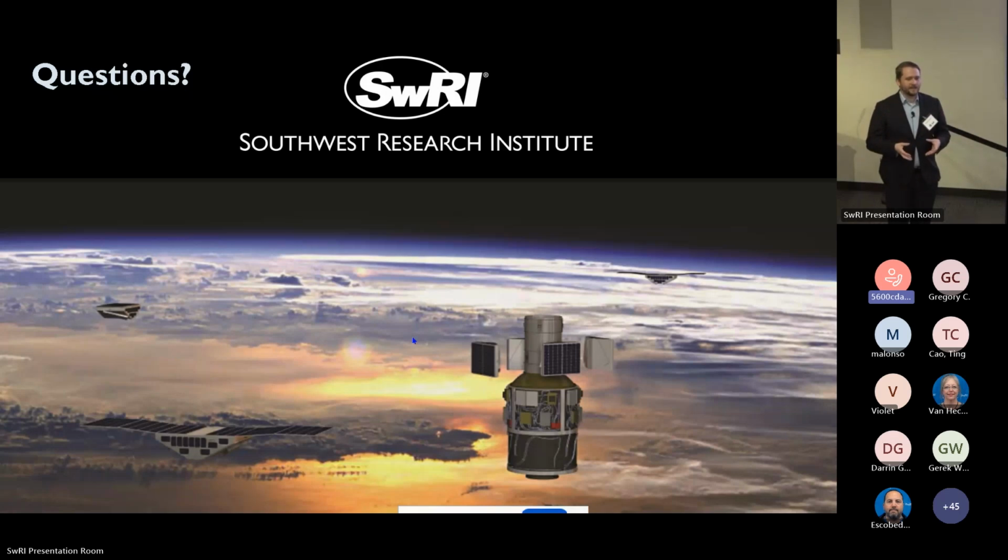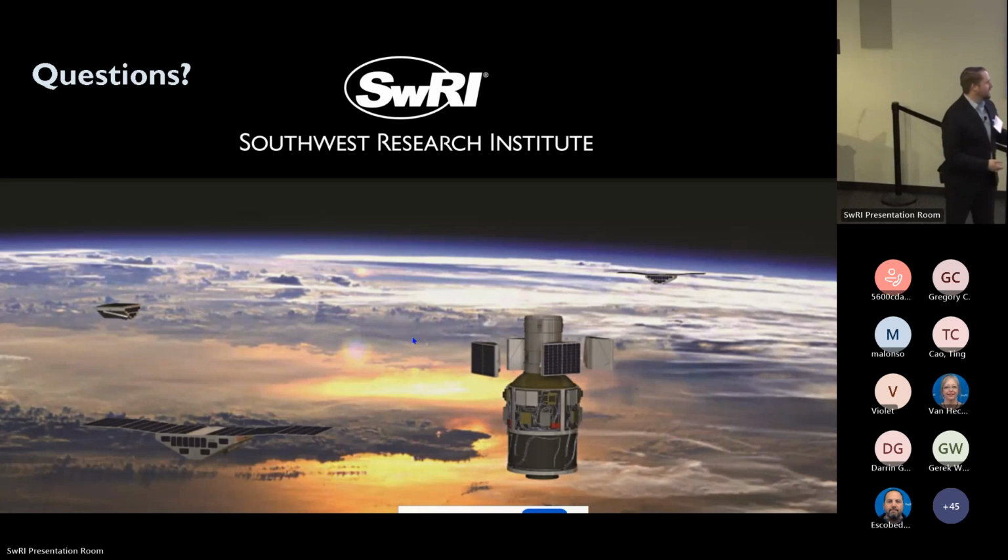All of the components of the satellite have to be defined in what's called an sc.txt file. It's where you list out your actuators, your sensors, and generally how the spacecraft looks. But if you want to change how your spacecraft orbits, like right now we're orbiting around Earth, if we wanted to send Cygnus to Mars, we can say, hey, now you're orbiting around Mars, and it's going to take care of all of those physics properties for us.